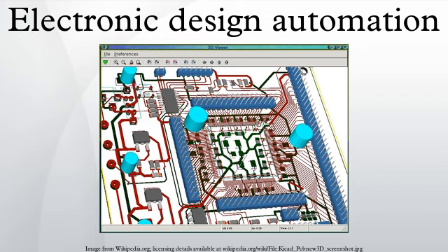Simulation. Transistor simulation, a low-level transistor simulation of a schematic or layout's behavior, accurate at device level. Logic simulation, a digital simulation of an RTL or gate netlist's digital behavior, accurate at Boolean level. Behavioral simulation, a high-level simulation of a design's architectural operation, accurate at cycle level or interface level.